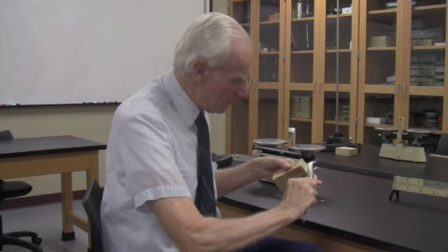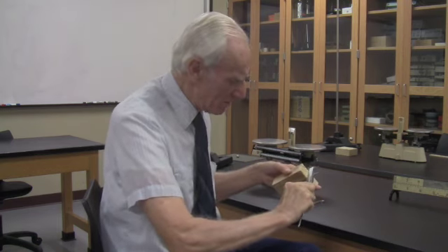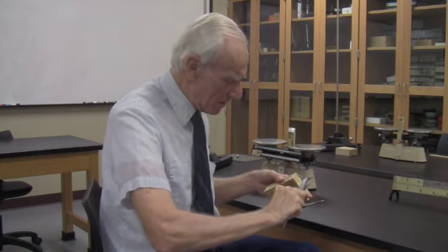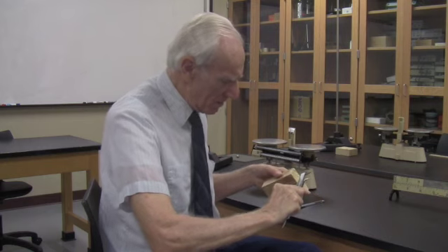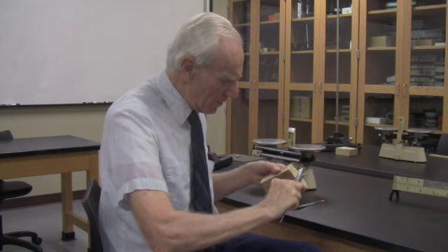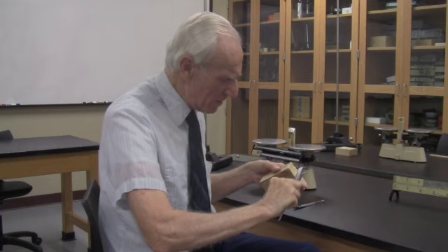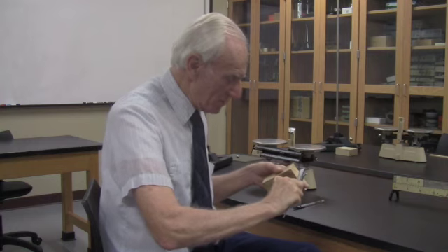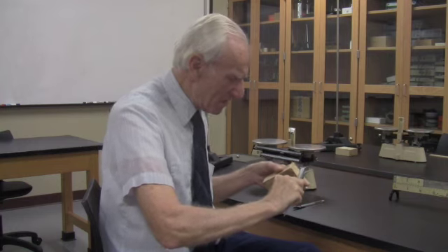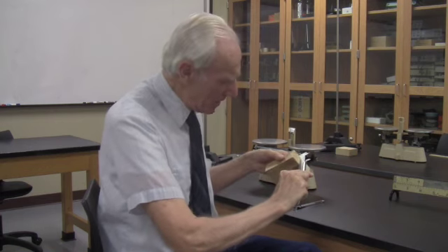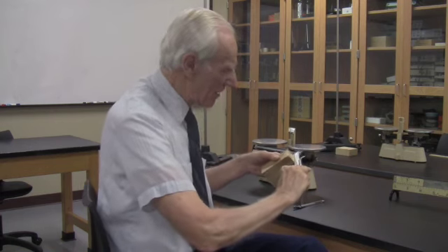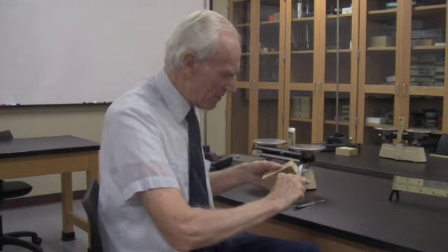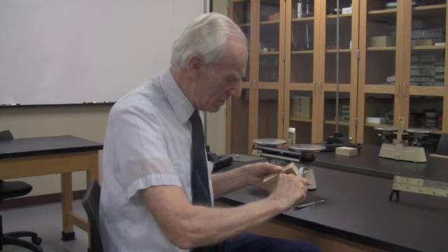So I'm going to read this, and I can't show you this because it's too fine and too far away, but this reading is going to be, I'm reading from the index mark. So the index mark is between 3.6 and 3.7, really close to 3.7, but below it, centimeters. Okay, 3.6 something centimeters. And so to find that something, you look up and down the scale here, and the scale on this caliper has 5 times more markings than the scale on this caliper, making it a little more accurate.